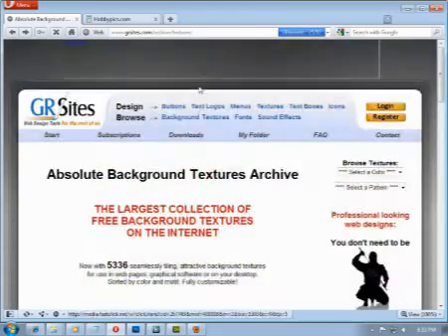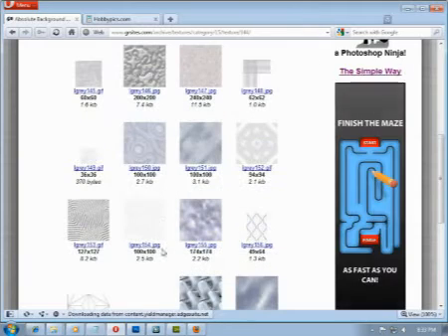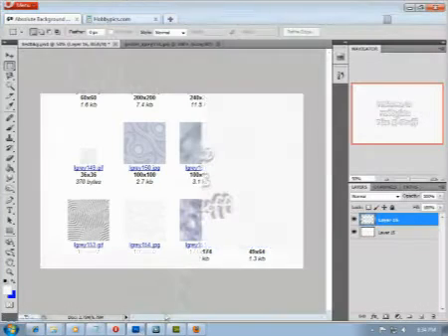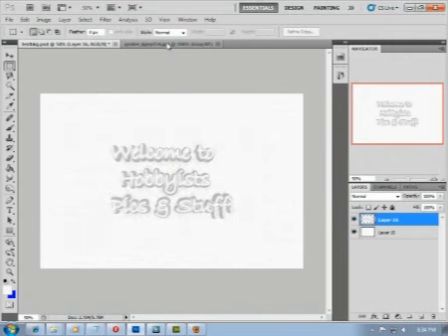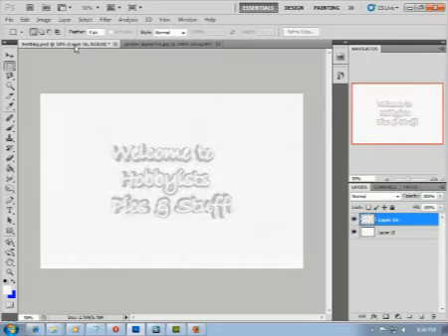In background textures, I found one I liked under light gray on page 10. So I helped myself to a copy of this L Gray 154. And we're going to want to remember that it's 100 by 100 pixels. We'll need that when we get to setting the tiling values in 3ds Max. And back in Photoshop, here's the JPEG. I tiled a few of them together to make that little test background we saw earlier.